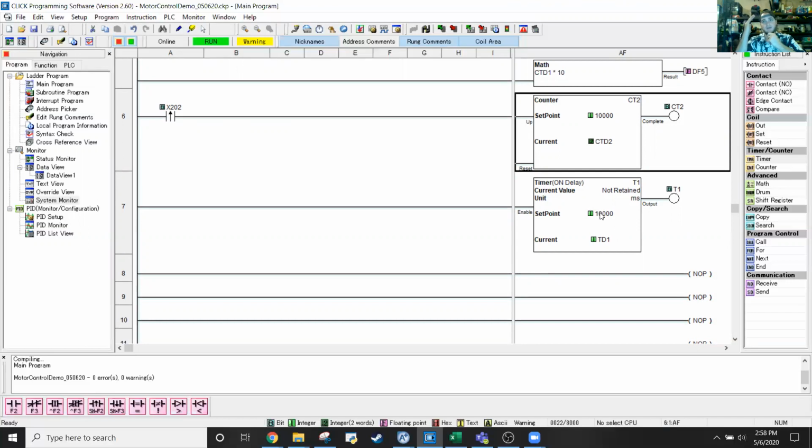Okay. And you're going to want to have that set up so that these reset every certain amount of time. Because if you don't, the memory bits that are accumulating for each one of the timer and the counter block are going to eventually fill up, because there's a limit on the size of integer that you can store in these memory registers. So I know that's kind of vague and non-specific. I want you to think about how to program this so that you can calculate the RPM of the motor based off that.